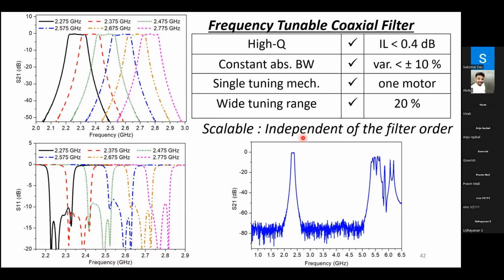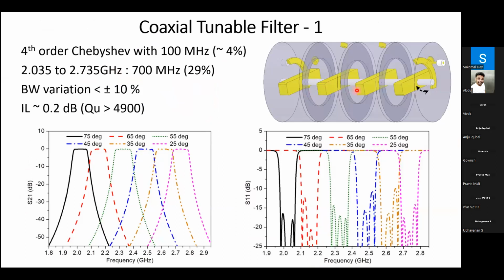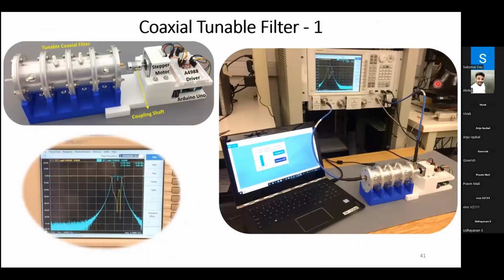Once again, the most important feature here is that it is scalable. That is, the single tuning element is independent of the filter order. So we demonstrated a 4th order filter, whereas we can design a 6th order filter or an 8th order filter with a single tuning element and achieve the desired frequency response.